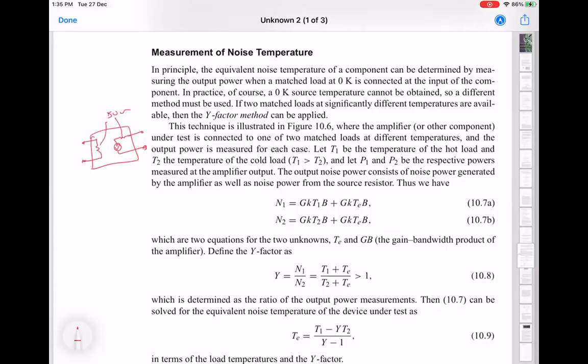Most real amplifiers have impedances close to 50 ohms, but they are not exact. So again, in the context of return loss, we measure this as, okay, if it is better than 20 dB, then we know it's close enough to 50 ohms. But usually they are not perfect. They will be slightly mismatched, but not by a lot.